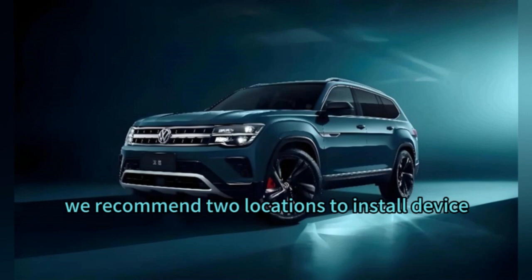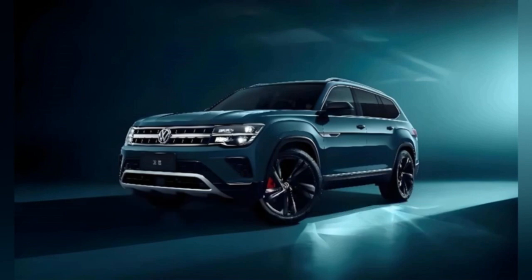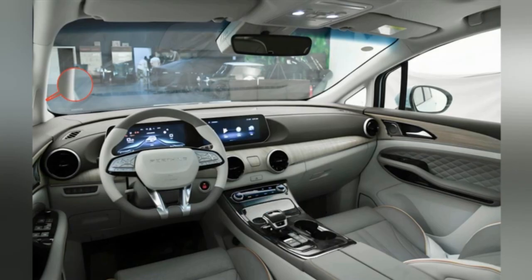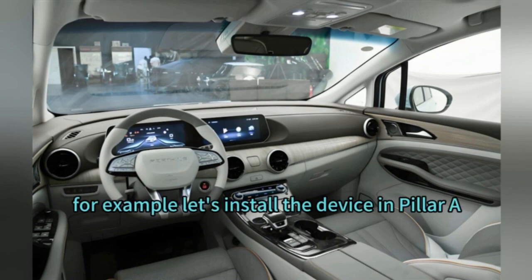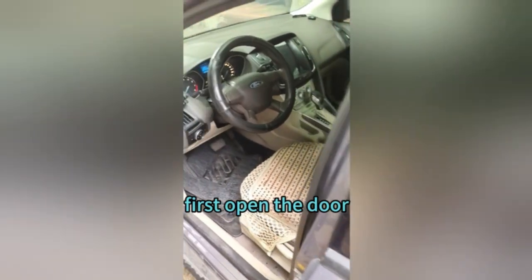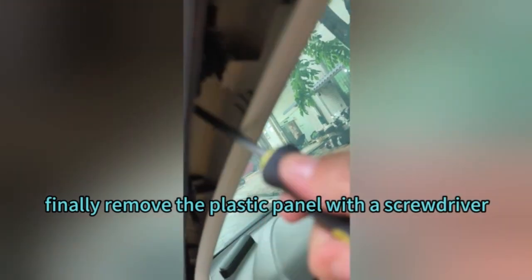We recommend two locations to install the device. One is pillar A. The other one is pillar B. These locations can get the best GPS signal. For example, let's install the device in pillar A. First, open the door. Then remove the tape. Finally, remove the plastic panel with a screwdriver.